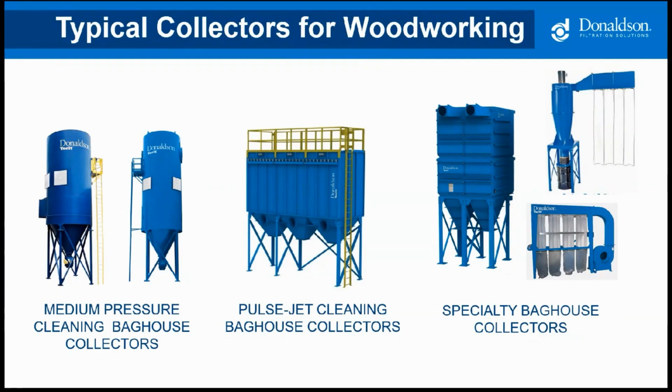Our baghouses are broken down into 3 different cleaning types: low pressure cleaning, medium pressure cleaning, and high pressure cleaning. The high pressure cleaning would be a compressed air system that reverse pulse jets the unit. Enclosureless collectors are limited to no more than 5,000 CFM by NFPA.